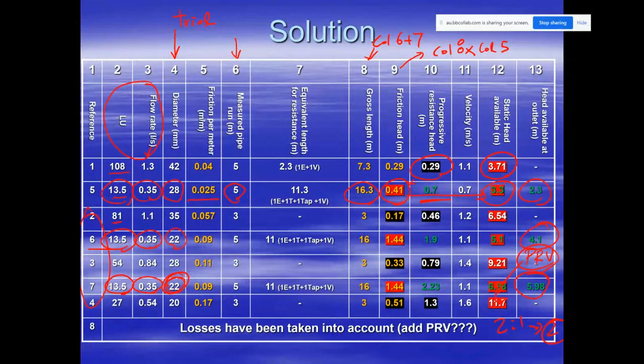Understand? Now, some students, they are very interesting. They add a lot of pressure reducing valves for their design. I would say totally wrong. Practically, for every 10 floors, we may reserve 1 PRV. This is the norm. If I go through your design and each 4 floors you add 1 PRV, I would not read in detail. I would say your design is totally incorrect.